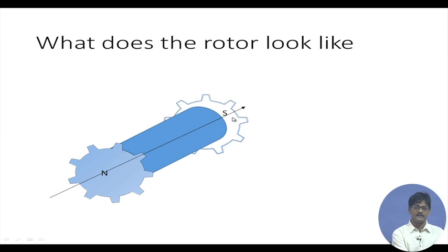There is one angular stagger of half a tooth, so that in the line of sight, if you look at the rotor from this side, you will find one north pole to be residing exactly in the middle of two south poles on the other side of this particular rotor, and the whole thing is a permanent magnet.